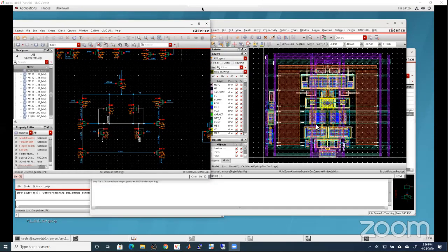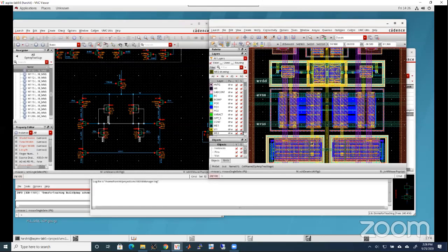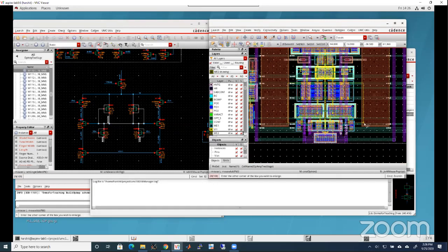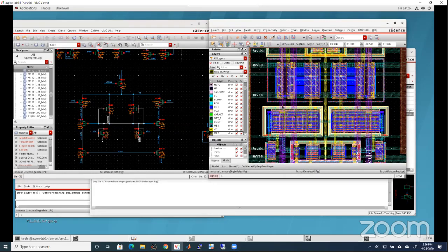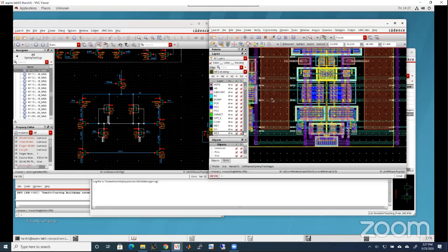And signals also. You can see here, for example, that metal 2 is yellow and is always going vertically. I followed that convention. Metal 4, this purple line, is also even and goes vertically. And metal 3 is odd, so it goes horizontally.